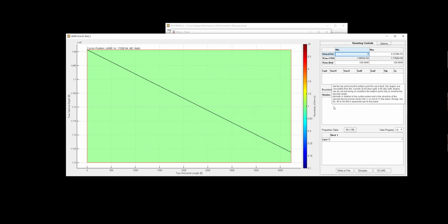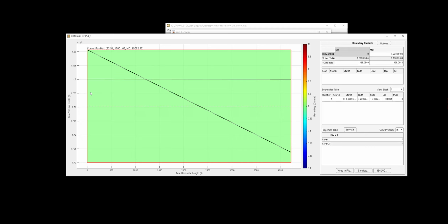And then we have tables for the faults and boundaries. What I'm going to do first is, since we saw that each block, which is what the faults divide this into, had three or four layers, start by adding four layers in here at approximately the right position, or four boundaries, I should say. Then when we add the faults, they will automatically divide these up into separate blocks.